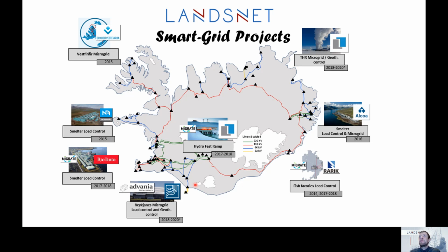The latest projects we've been focusing on are with the geothermal plants, both here in Theistareykir in the northeast, and also a little bit here in the Reykjanes Peninsula, where we're trying to have the geothermal units react according to disturbances in the grid. In the past, geothermal plants have not been the regulating units in the system, and now we're experimenting with giving them signals to either change to frequency control or do some fast ramp control on top of any other regulation in the grid during those large disturbances.